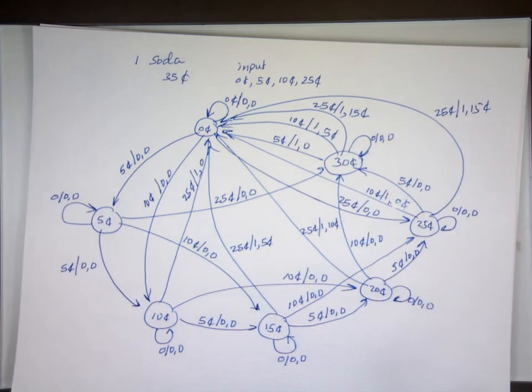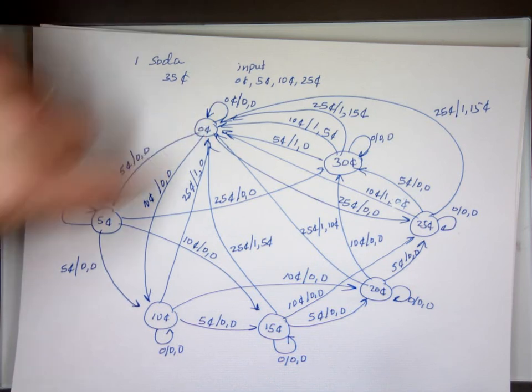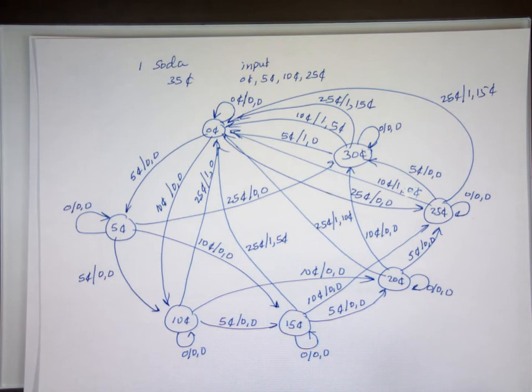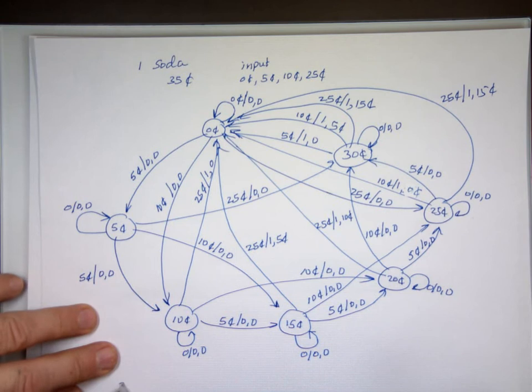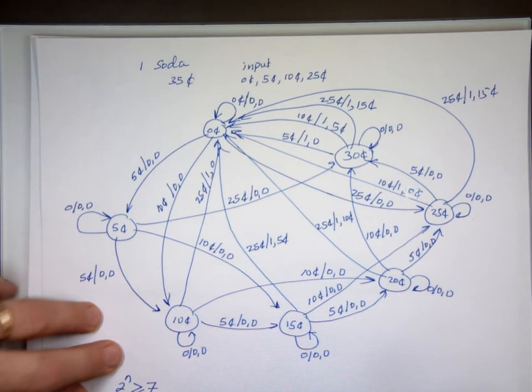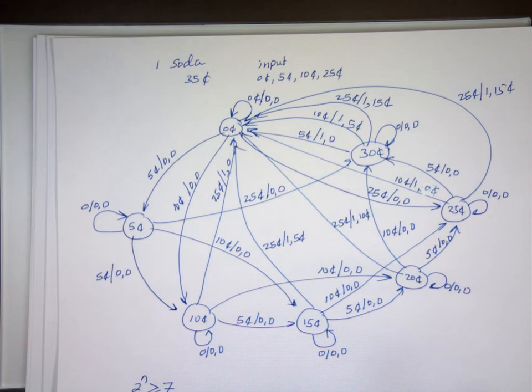Now it seems ugly, but when you look at it, really, how many states do you have? 1, 2, 3, 4, 5, 6, 7. How many flip-flops do you need? About 3. Oh, 2 to the power of n has to be greater than or equal to 7. If n is 3, what's 2 to the third? 8. Is that bigger or equal to 7? Yes, 3 flip-flops.